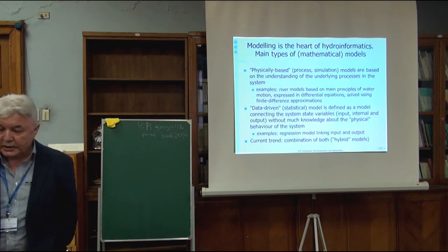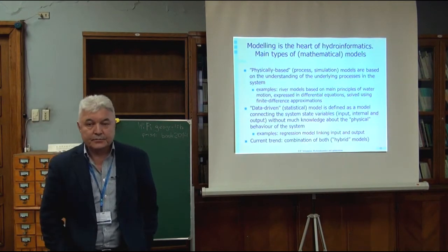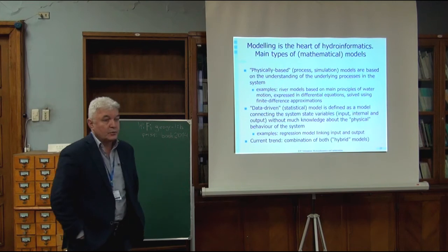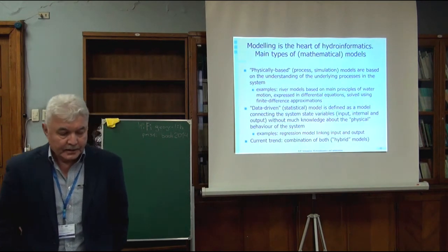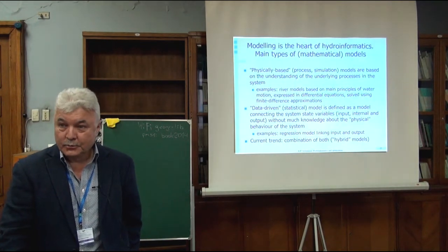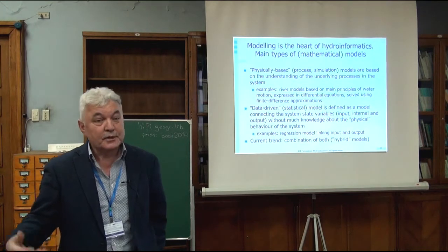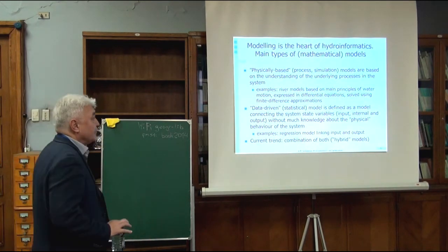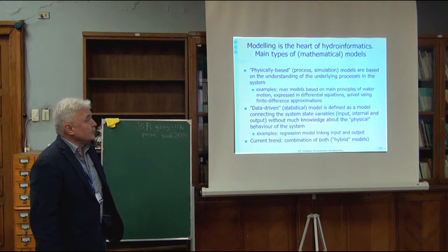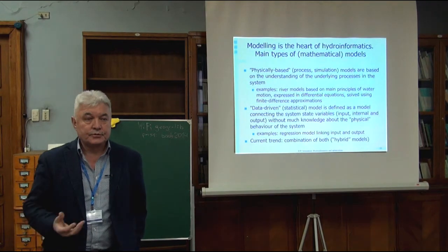One of the most important and widely spread tools in modeling is physically based models. We take the basic principles, which are Newton physics, and we write the differential equations describing the water motion. Can we solve these equations, by the way, analytically? Good, excellent. We cannot. So we use numerical methods to solve these equations approximately, but actually it's enough. Accuracy is enough because data is anyway bad. So physically based models are the mainstream models which are used everywhere.